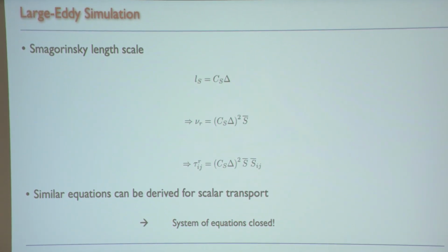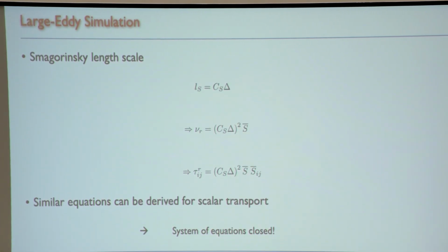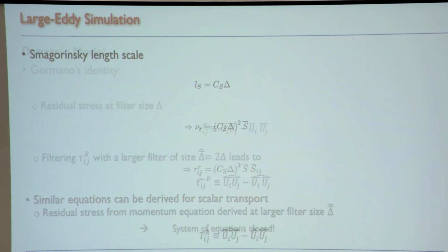But you know a part of the turbulence, so you write that model for the part of the turbulence that you know, and from this you can determine what coefficient you would need so that the model for that part of the turbulence is correct, okay? So that determines the coefficient, and you say, I determined this on the large scales, but it should be valid also on the small scales. That's what the dynamic model does.